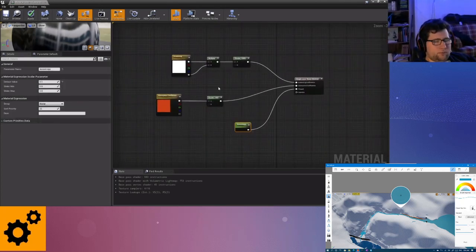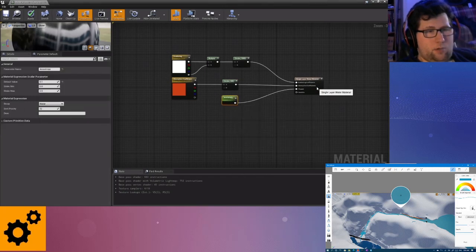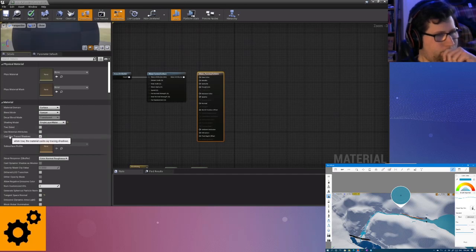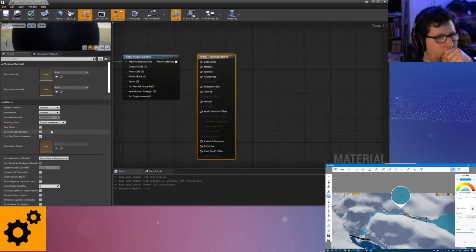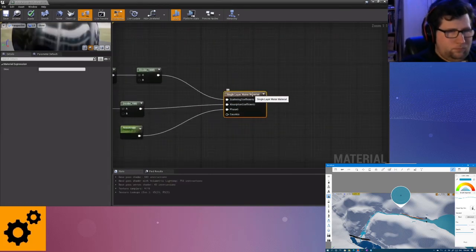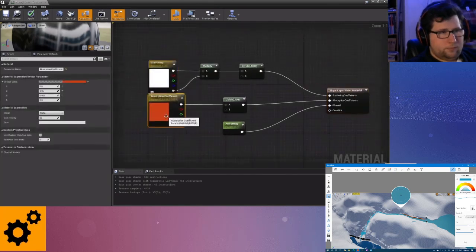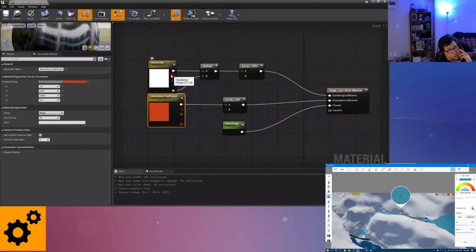And then down here is where we get to the actual meat of what's new with single layer. So obviously this material is using the single material attribute pin, but normally this is the material input. Single layer water adds this additional single layer water material input. And what that does is it allows you to specify your scattering and your absorption coefficients. So that's really what causes the blue coloration and the nice scattering inside of the water.